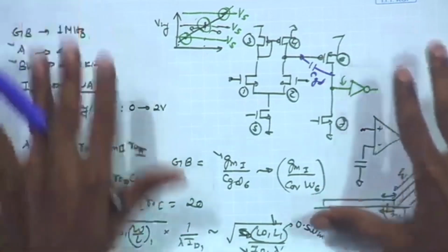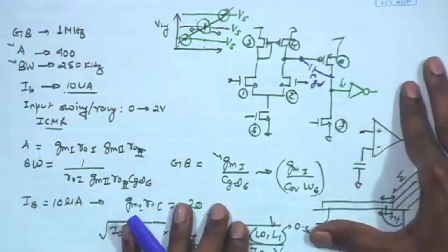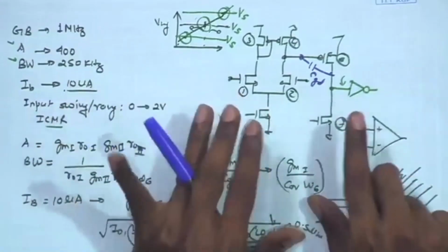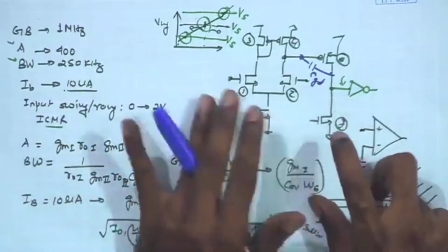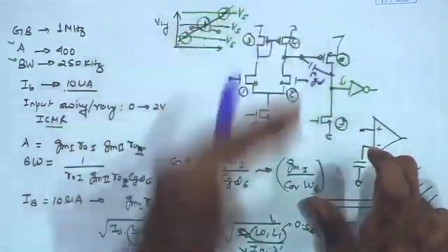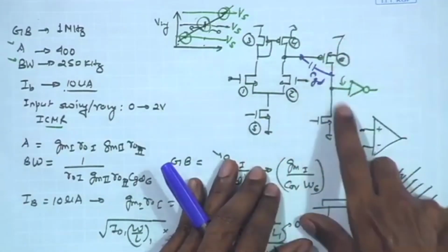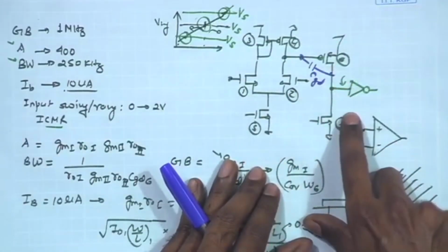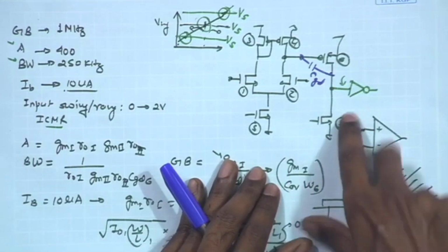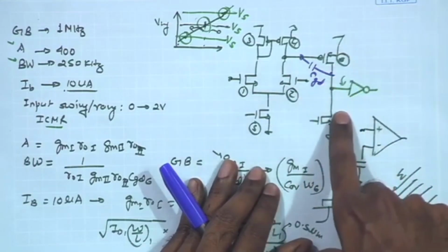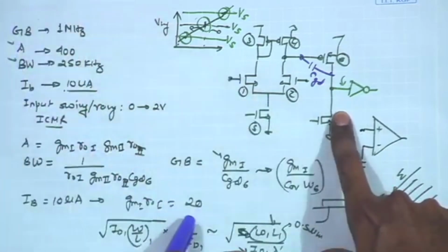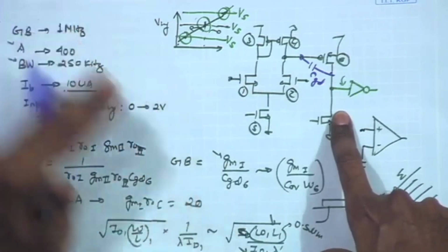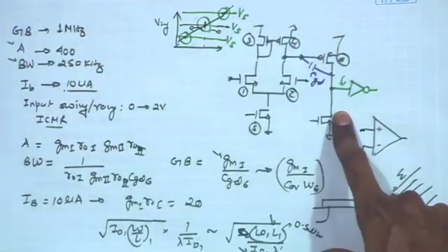So, there is no unique algorithm, there is no unique set of steps. Depending upon the specification, depending upon the requirement, the load conditions, etc., you may have to look at your sizing consideration. If the condition had been different and you had a large load capacitance over here, so that the bandwidth dependency is really over here, then the sizing constraint would be different. So, here I have just tried to derive the sizing consideration for this particular condition.